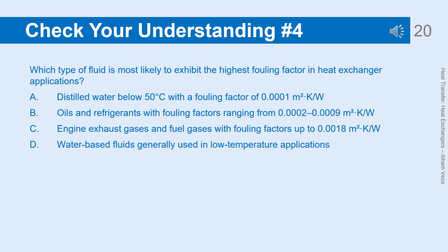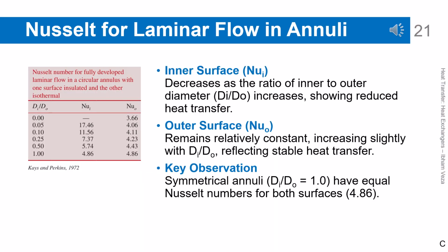D. Water-based fluids generally used in low-temperature applications. This is incorrect because water-based fluids, especially at low temperatures, typically have low fouling resistance compared to high fouling fluids like engine exhaust gases. Nusselt numbers for laminar flow in annuli.